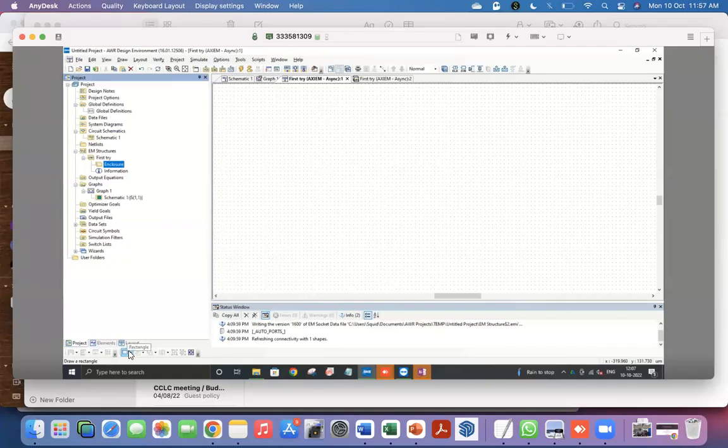Now, for more sophisticated structures, you can actually use any CAD software like AutoCAD or other things to draw your structures, and it can be imported into this and then adapted for this. But for very simple things, like simple sections of transmission line, you can just use their drawing tools. They have some very simple drawing tools here. And for a microstrip, you just need a rectangle, right? So here the x-axis is the horizontal axis and the y is vertical.